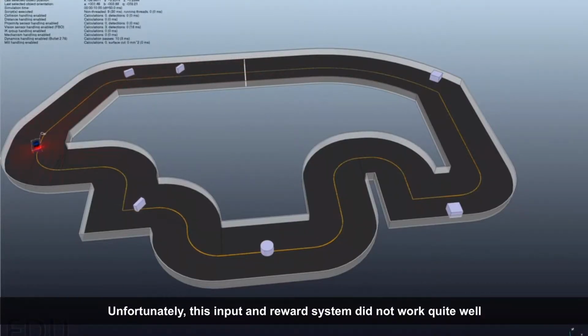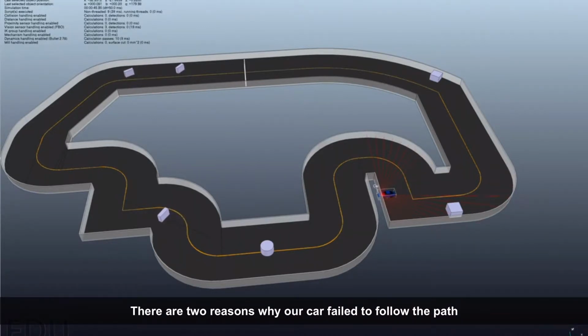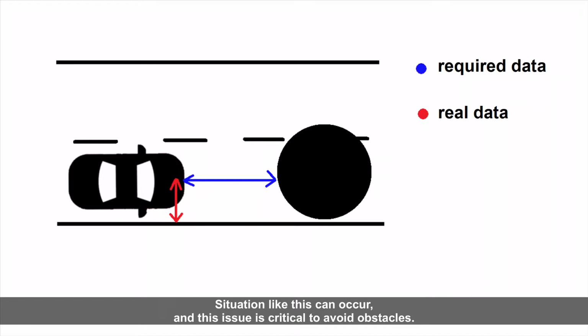Unfortunately, this input and reward system did not work quite well. The extreme curved section was too difficult for our car to go through. There are two reasons why our car failed to follow the path. First, the target change was too abrupt for our model, and this immediate change was not suitable since our car tends to get to target linearly. Secondly, minimum LiDAR data was too limited. Situations like this can occur, and this issue is critical to avoid obstacles.